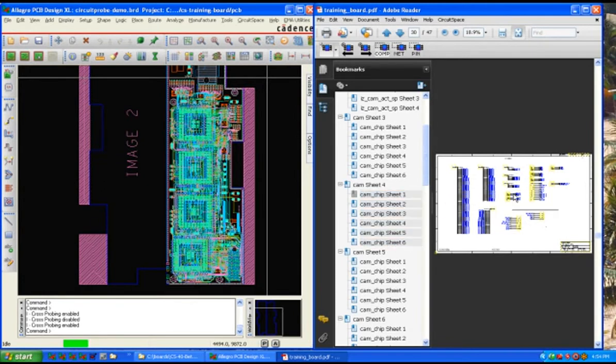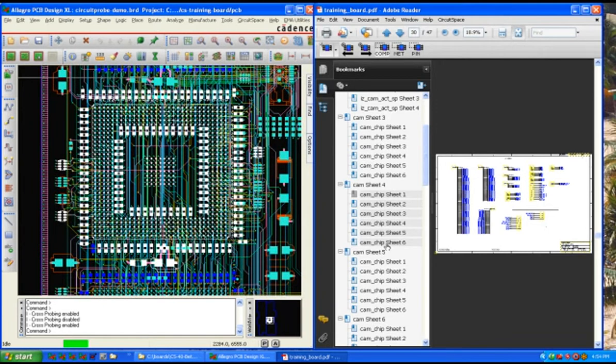So if I know that the hardware engineer wants to take 6 pages from a previous design and copy and paste them into his new schematic, I would actually just call up that old schematic, call up the previous design board, make that selection set, and now you can see all the components that are highlighted are currently members of this cluster. However, if I would have manually defined this cluster and put a window around this part, you would see that these extra parts here, these extra resistor arrays, there's a resistor here, a couple other resistor arrays, and some other termination in here that would have been assigned as membership.